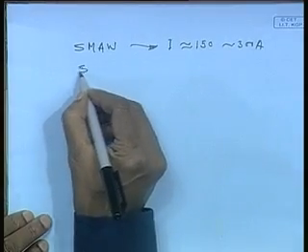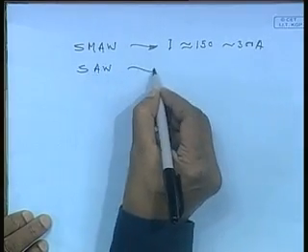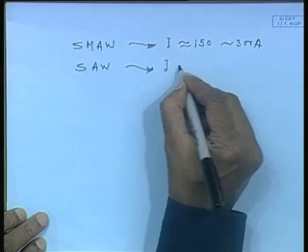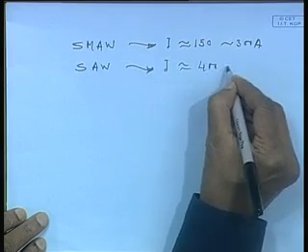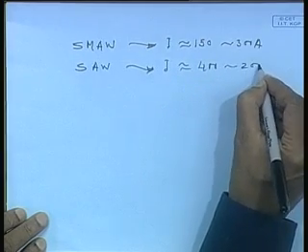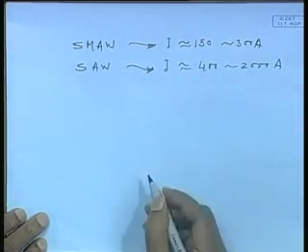Whereas, as we have discussed in submerged arc welding, the current level could be, say, around from 400 to say 2000 ampere. So, you can see the heat generation is much higher. So, more heat does not mean that more distortion, it is the rate of heat input, that is what actually influences extent of distortion, right.